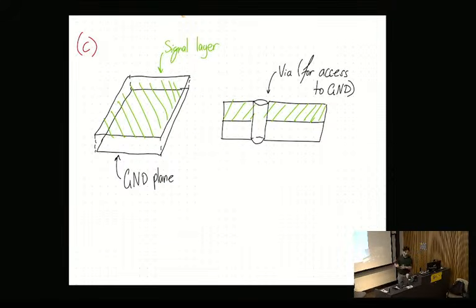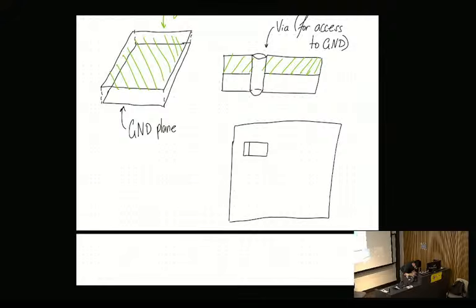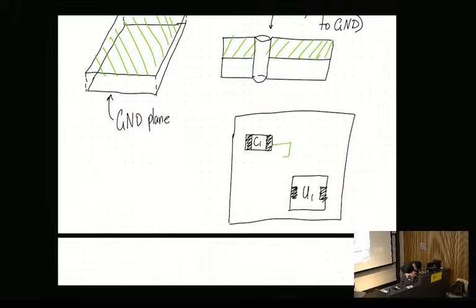Okay, so we're here now. We have our ground plane. Now we need to analyze where the parasitics are because that's what the question is asking us. So if I were to make a sloppy PCB, and I had my capacitor here, so we were given a capacitor C1, and then the PLL chip or the clock generator I put down here, and it has 2 inputs. Now let's say I route this trace like this. So this is my routing.